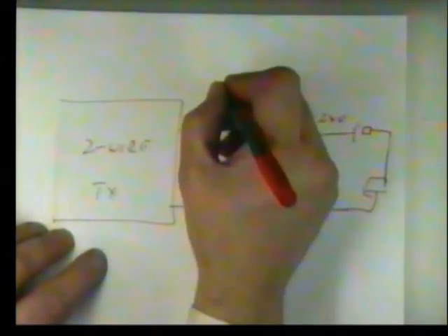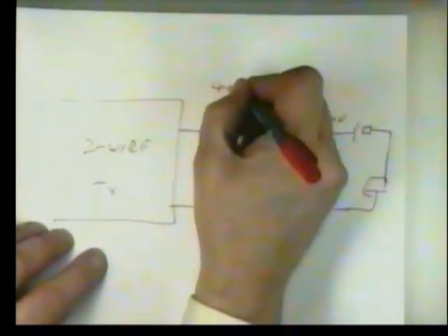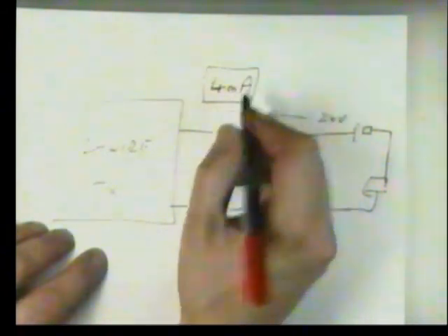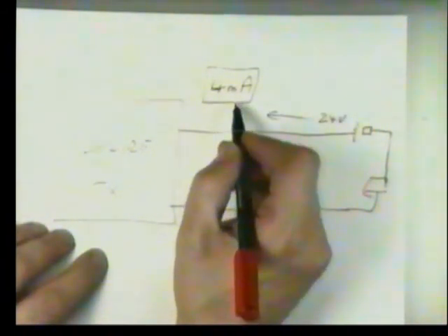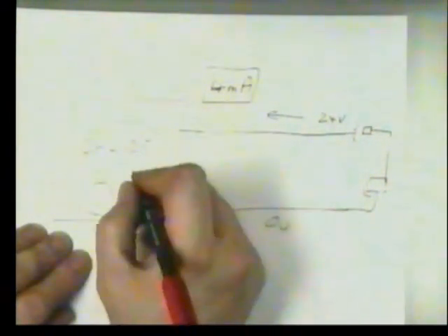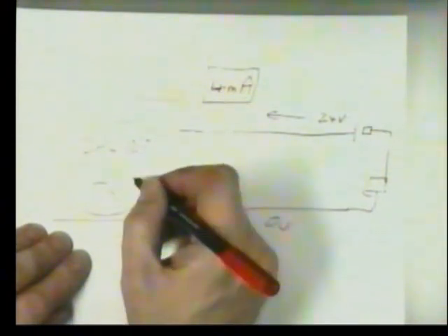How do we use this concept in a transmitter? Well, all transmitters use 4 milliamps of power as standard. 4 milliamps. It's minuscule and it's nothing. It's a very small amount of power. That is the bare minimum required to power the whole of the electronics and the transmitter system.